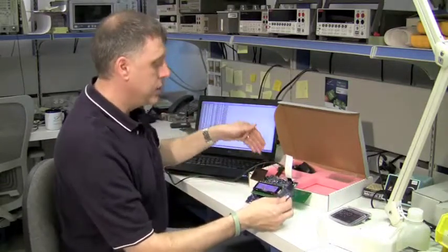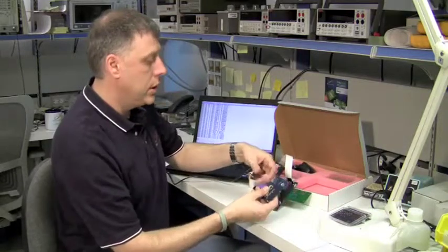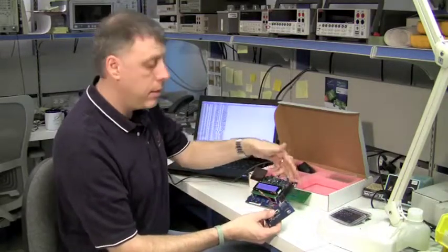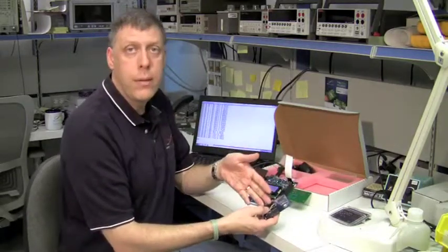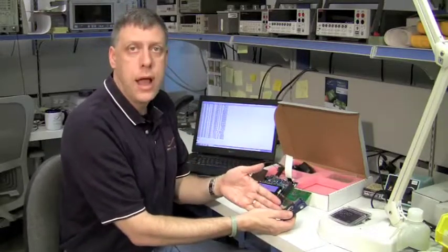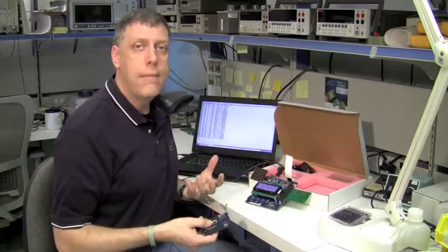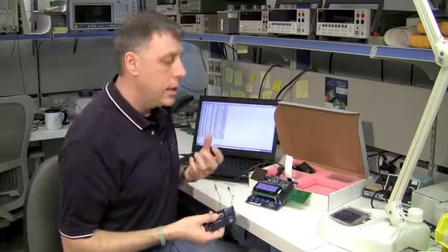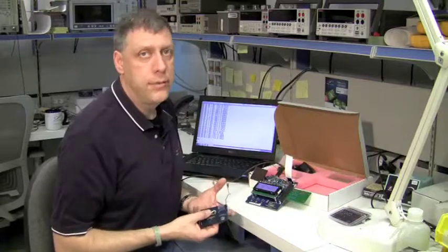But in this case, I can use this external solar panel to recharge this MEC on the ADP kit, which I can then use to power my external application. So here I can model a solar panel powering my external application and determine over time whether or not I have energy balance. Energy balance is a very important concept in energy harvesting.